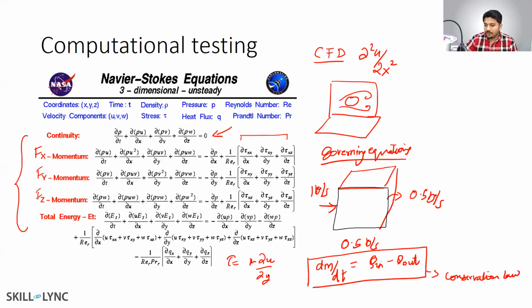So if you take this expression, which you have studied in undergrad, and you take another derivative of that, right? Since it's tau xx, you'll basically get dou by dou x of dou u by dou x. So that's going to lead to dou square u by dou x square. So these are called the viscosity terms. They are also called diffusion terms, right? Because they help in diffusing the momentum, correct?